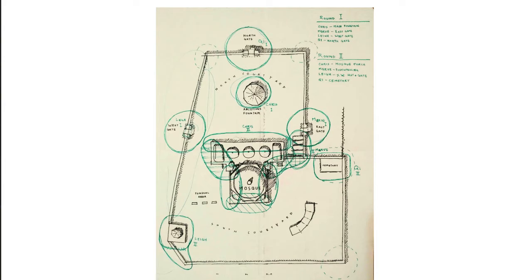And then, of course, depending on the size and complexity of the project, you can repeat those steps as many times as you'd like. Indicated here, you can see we planned to break down the porch and the sides and the outside of the mosque into separate campaigns, just due to the limit of photographs you can submit at once. And then the idea would have been to combine all of those completed photogrammetry models into one supermodel. So something very similar to the laser scanning method, where you do multiple scans and then combine them later.